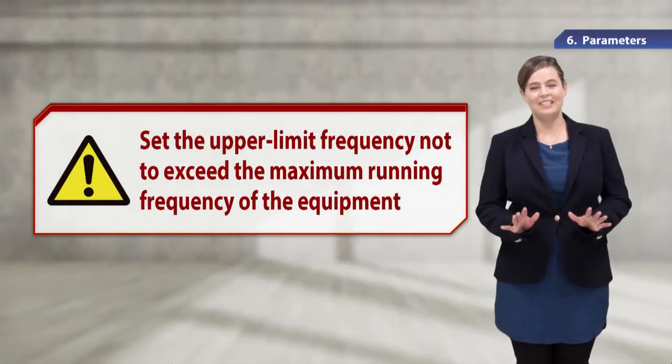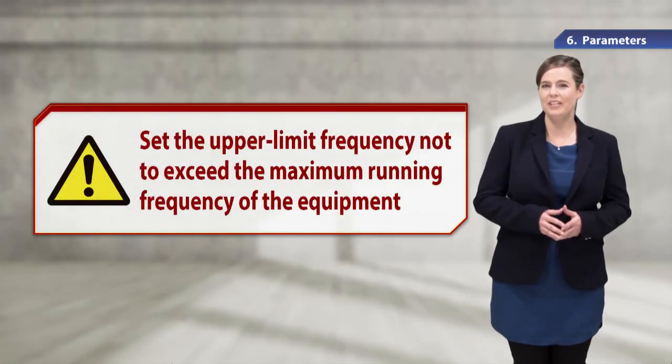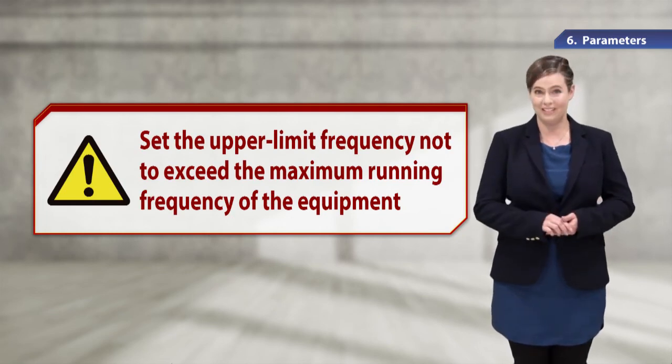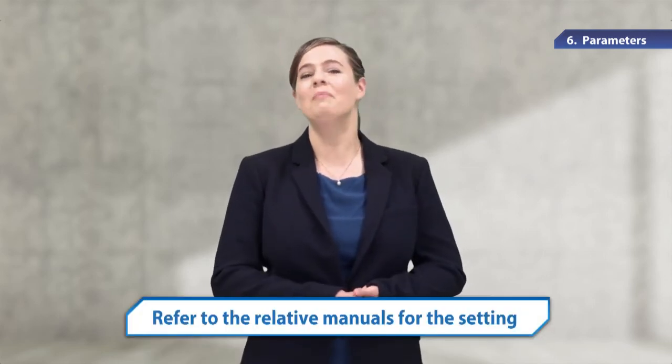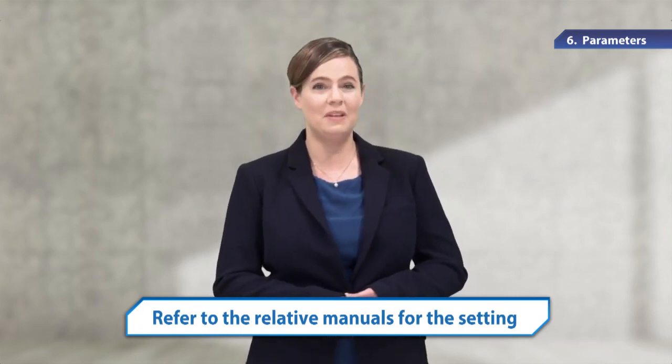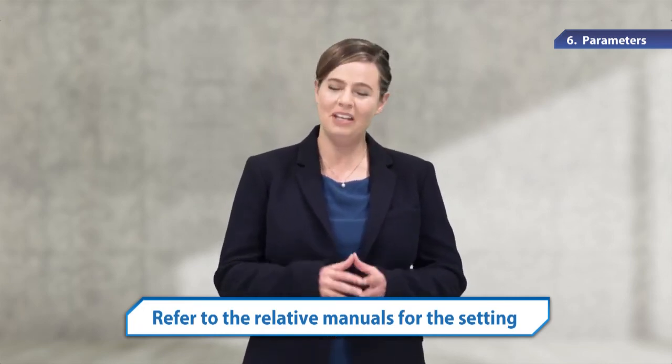For safety reasons, set the upper limit frequency so that it does not exceed the maximum running frequency of the equipment. We have learned the basic parameter settings of the inverter. For safe operations, please refer to the manuals and configure the settings that meet the operation specifications of the equipment embedded with the motor.